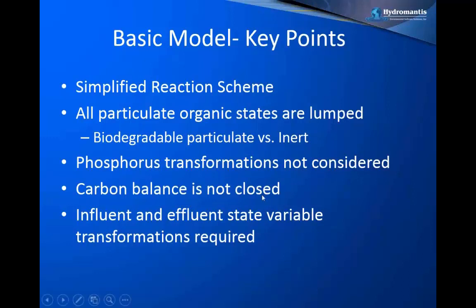Again, looking at the philosophy of this model's development, in this case it is an independent model, and it does require influent and effluent state variable transformation. So when we are connecting this model with the liquid train models, depending on which model we are using in the liquid train, we do need to have specific influent and effluent state variable transformation interfaces.